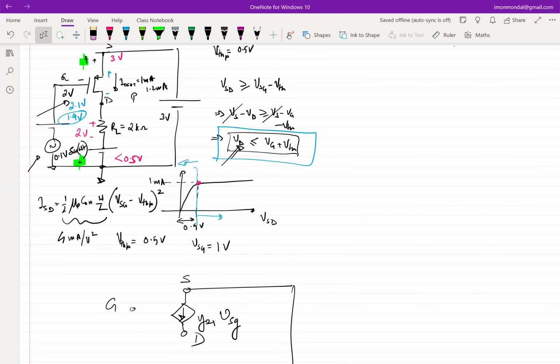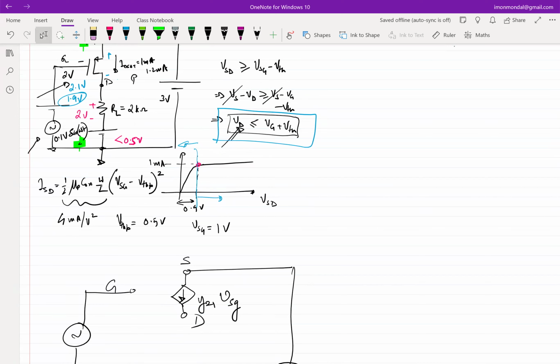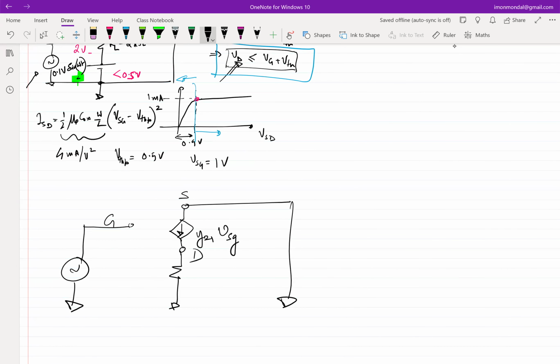What about the gate? So the gate has one constant voltage source and one incremental voltage source. So the incremental will remain, the constant goes off. So the incremental remains. What about the drain? It's connected to a load resistance RL. The incremental equivalent of an RL is an RL, right? So that remains, and the incremental equivalent of the other voltage source that is connected is 0. So that shorts off, right? So this goes here. All the shorts are connected together, so I can as well connect it like this.